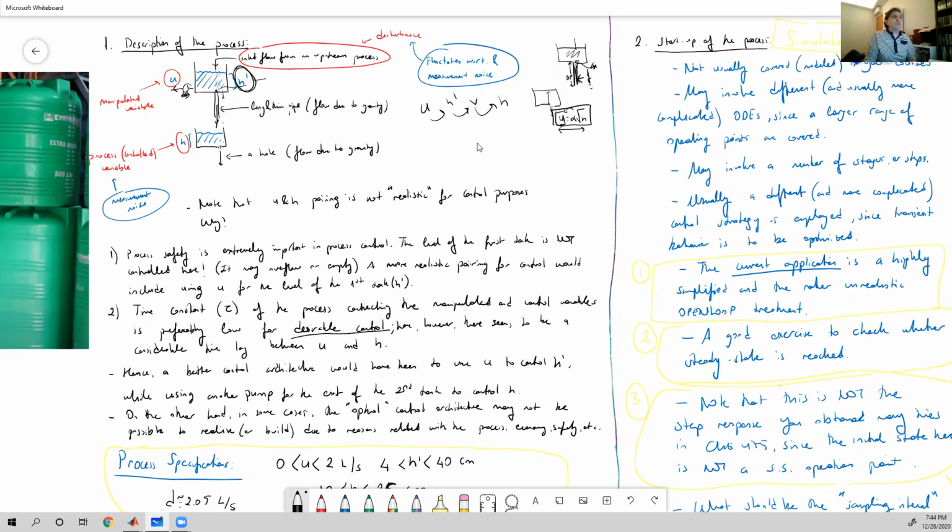So I'm not going to go into the details of the mathematical model, but understanding the mathematical model is an important step in understanding the dynamics of the process, the causes for some time lags. And the reason for the time lag is, when you put a thin pipe, you have an additional resistance to this process for the outlet.